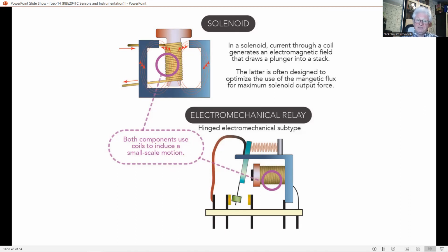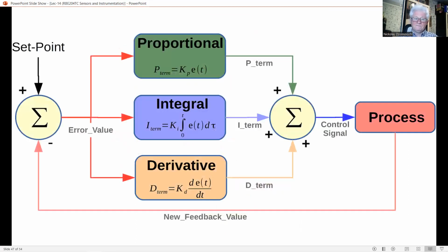An advantage of using a PLC is that the devices in a plant can be permanently wired, and the plant operation can be modified or restricted by software means or by properly programming the PLC without requiring hardware modification and reconnection.